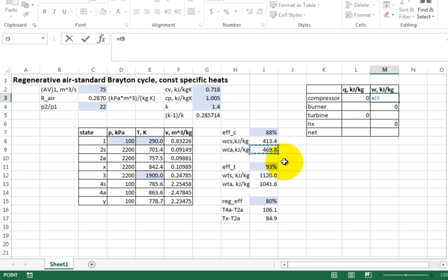That's the compressor. At this point, I like to put the negative sign because I like to sum that column. And so this is a negative amount of work coming out of the compressor. It's a negative out of the compressor, which is into the compressor. Okay. How about for the burner? That's going to be my specific heat times my change in the temperature. The burner has to take it from 842.4 all the way to 1900. So 1900 minus 842, close paren. And that's what it provides.